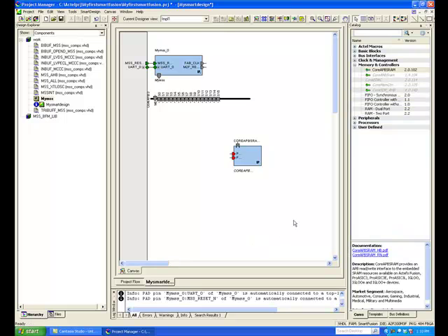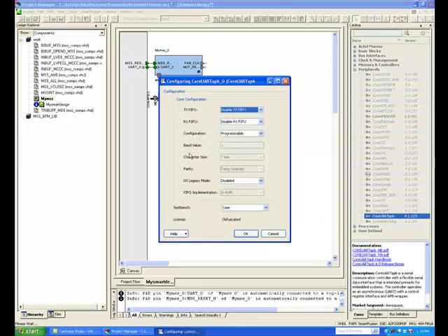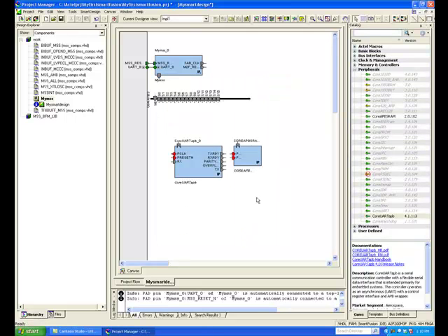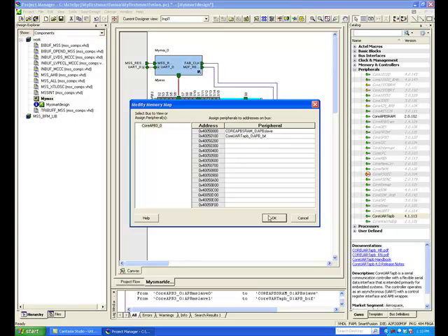Next, in the Peripherals category, click and drag the Core UART APB onto the canvas. Change the TX and RX FIFO settings to enable and click OK. Now, right-click the Core APB3 bus interface instance and select Auto Connect Selected Instances. Accept the address settings on the Modify Memory Map by clicking OK.